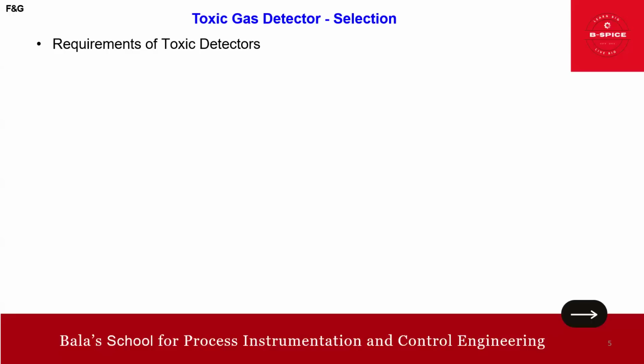Okay, friends, you got it right. So the field mounted toxic detector shall be selected to detect gas leakage in working areas of open outdoor installation. And another point is the toxic gas detector shall be configurable and it shall be possible to calibrate the detector. Similar to what we covered in the flammable gas detection, toxic gas also shall have an isolated 0 to 20 milliamps 3-wire analog output for transmitting status information to the FGS system, configurable as per NAMUR NE43.